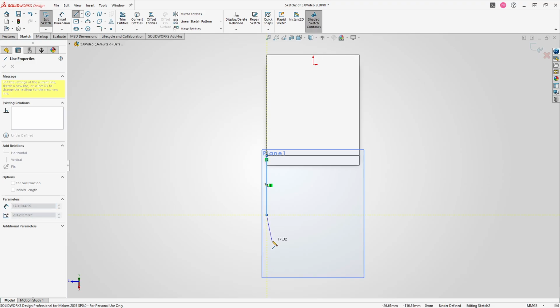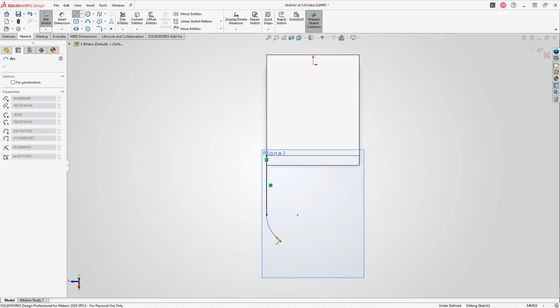And then my new favorite shortcut here is when you're in the middle of a line tool, you can either go out and then back into this vertex to switch to an arc. But if you hit the A key, because my left hand is always on the keyboard, it switches between arc and line. So that's kind of nice.